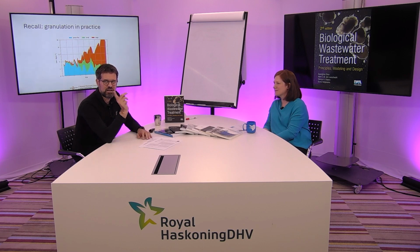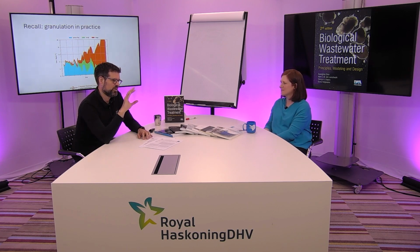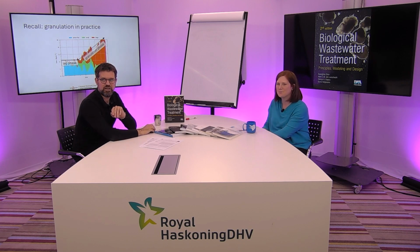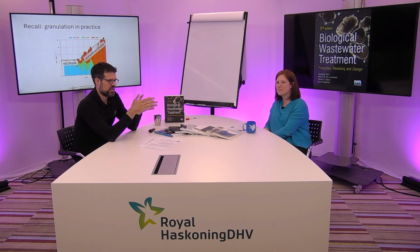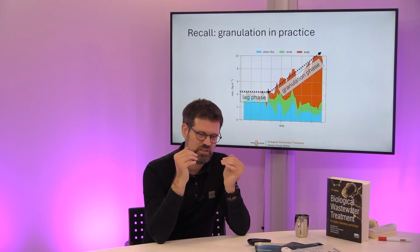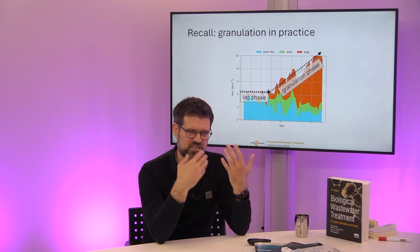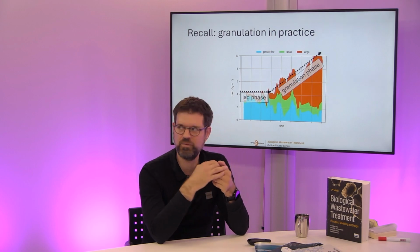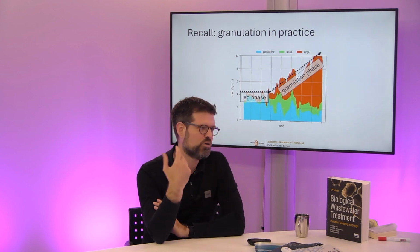And if you look at the presentation and recall how it looks in practice, we kind of have a lag period. Yeah, the lag. So you see that it takes a few months, a lag period in this case, and then suddenly the granulation kicks in. You have these flocs, they are present, and then the small granules grow in, and then the large granules grow in. And we see that over and over again happening.